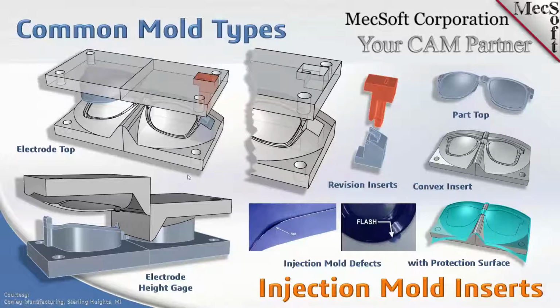Okay, so on the far left, if you've created cavities, then you know about EDM machining, electrical discharge machining, where you're taking a core and a cavity, and one half of the cavity is typically made out of graphite, and it is used to actually burn a cavity into your insert.